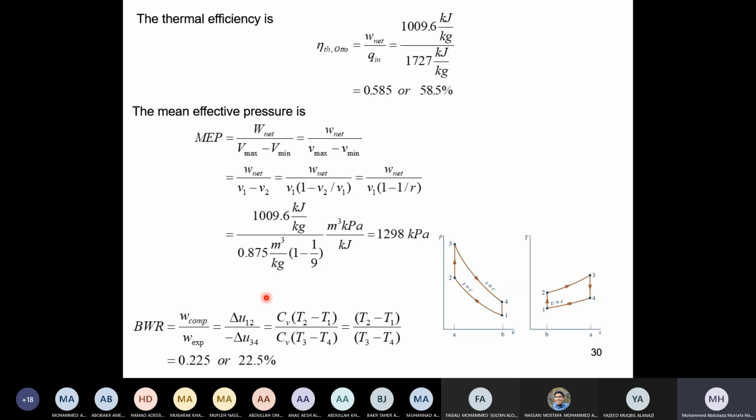I don't intend to complicate it more than that, but in some cases, you may be given an efficiency for the turbine, and you may be given an efficiency for the compressor. And of course, you know how to do that, and therefore you can use 3 and 4 prime and 1 and 2 prime. This is similar to what we have done in the previous case. But in this chapter, you can always work considering the ideal gas situation. Any question here before I go to the next cycle?